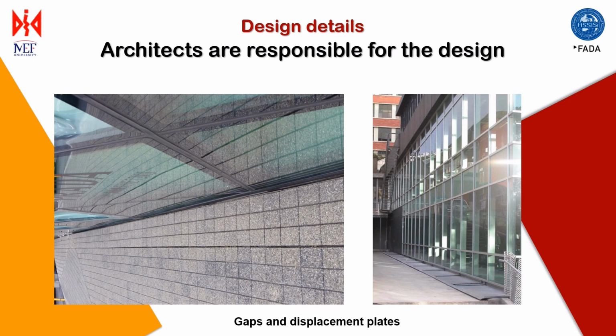As well as moat covers and other flooring movement joints, capacity for seismic movement is also required when an isolated building connects to another building, be it isolated or not, at the roof, up walls, and along and across ceilings.